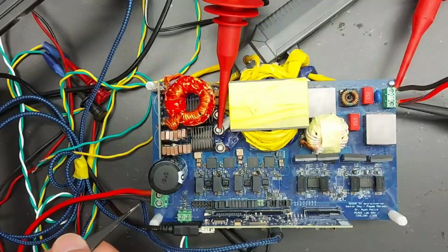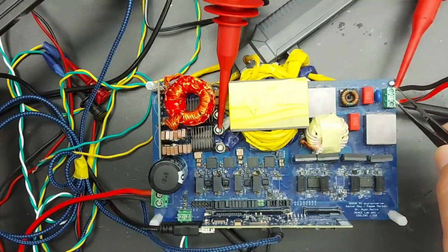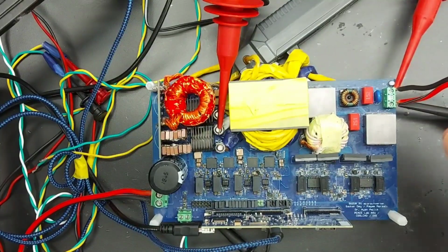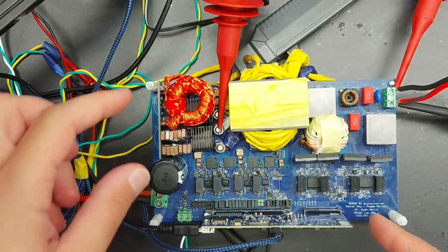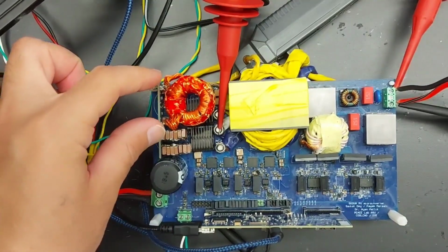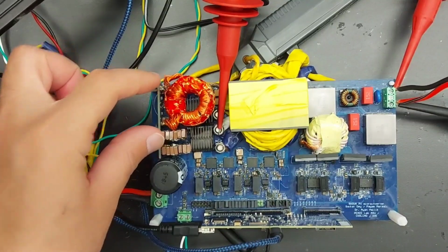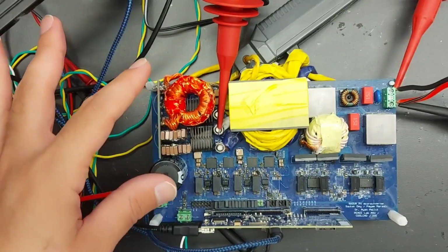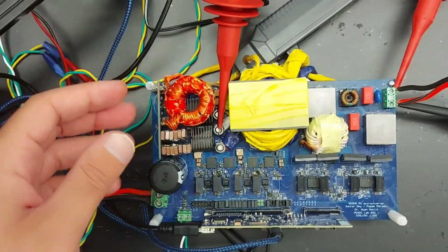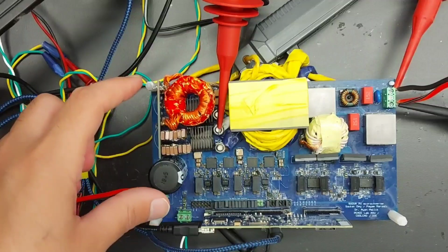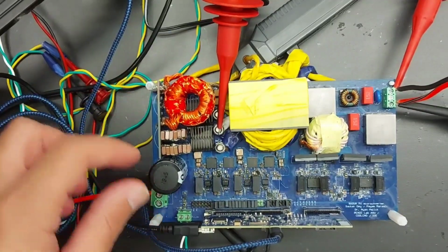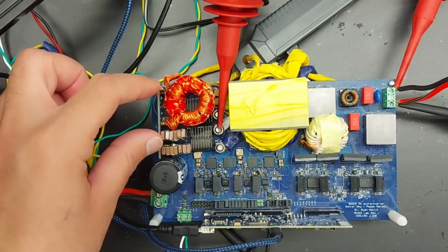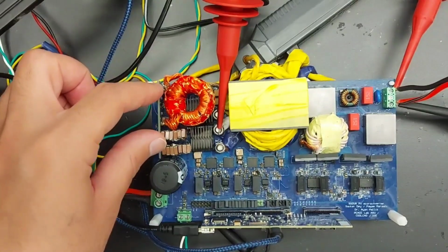As you can see here, we have the DC input that is connected to the solar PV panels, and here we have the output of the board that is connected to the grid, which is 120 volts RMS. Here we have the microcontroller, and this is the Power Pulsating Buffer, or the PPB, which is installed here to eliminate the electrolytic capacitors. The design is for 10 millifarad DC link input capacitors, which is realized by three different electrolytic capacitors, 3.3 millifarads each, and you can see that we can substitute those electrolytic capacitors with this PPB here.